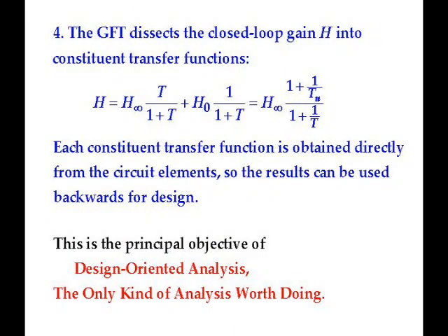Four, the GFT dissects the closed-loop gain into three or four constituent transfer functions, each of which is obtained directly in terms of the circuit elements, which makes it possible for the results to be used backwards for design. This is the principal objective of design-oriented analysis, the only kind of analysis worth doing.